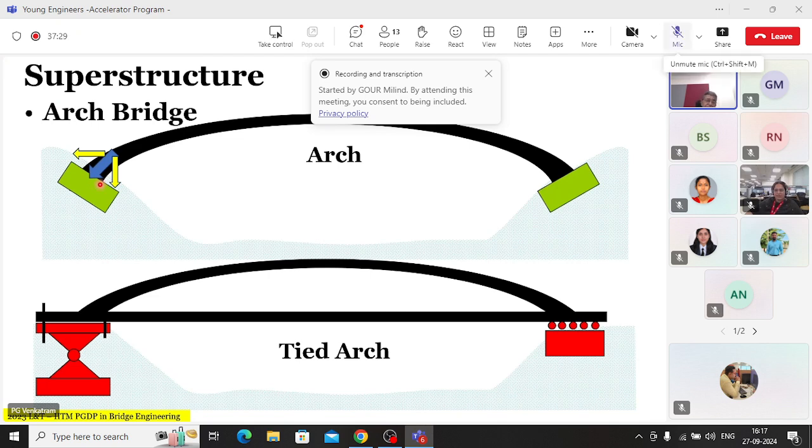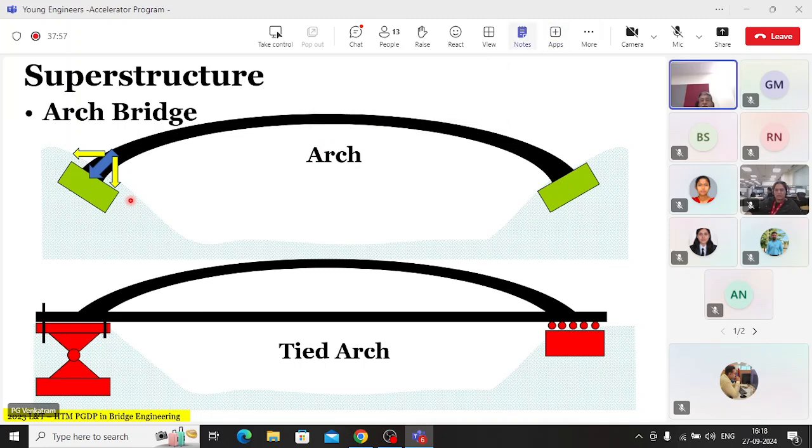So now the question, therefore, is where do you get the best shear strength in soil? In rocks. Stiff clay, no. Unlikely for you to get lateral resistance. Shear strength you will not get. Not much. Okay, compressibility might be reduced, but shear strength may not be much. So therefore you need something like a rock, which means what? A pure arch can be built only in what kind of terrain? Rocky terrain. Only in the rocky terrain.